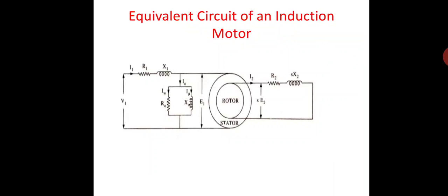So here the stator carries the field coil whereas the rotor carries the armature coil, and the stator winding is connected to the supply V1 whereas the rotor is connected to the load. Now we are giving three-phase supply to the stator coil. You know that a rotating magnetic field is created. Due to the rotating magnetic field sweeping over the rotor conductor, it is cut by the rotor, by electromagnetic induction, that is Faraday's law of electromagnetic induction. So there is an EMF induced in the rotor coil.